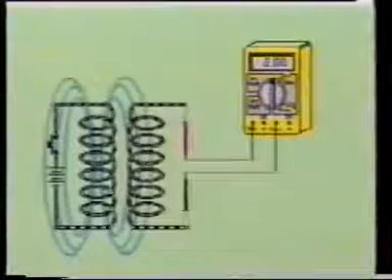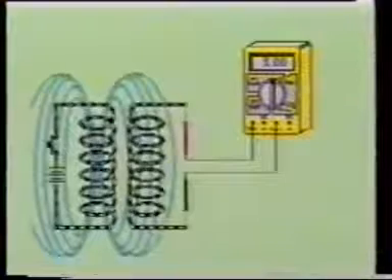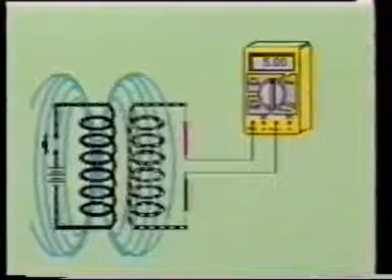This induced voltage will be such that it will be in a direction completely opposite of the direction of the current flow. Because of its opposing direction, it is called a counter-electromotive force. The effect of this counter-electromotive force, which builds up in the conductor, is to oppose any increase in current. At the instant the current begins to flow, the lines of force will be expanding at their greatest rate, and the greatest value of counter-EMF will be developed.